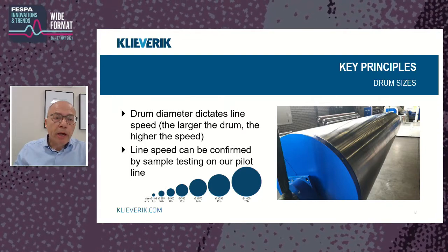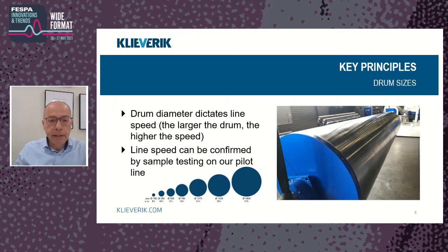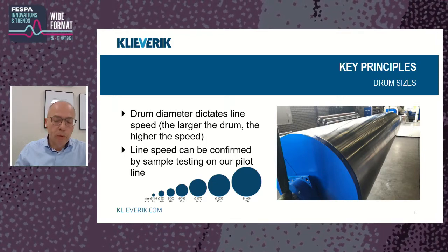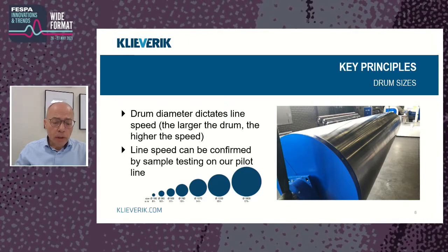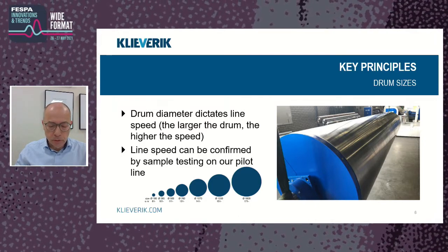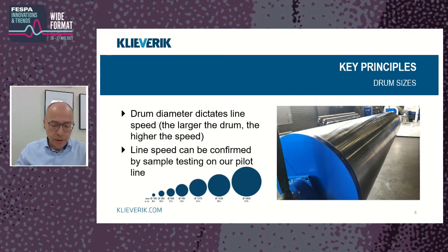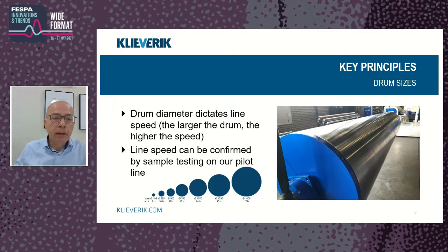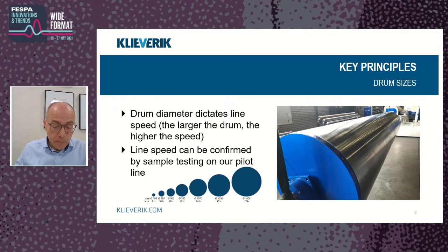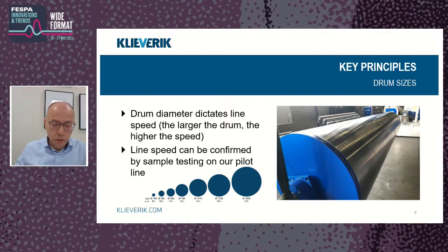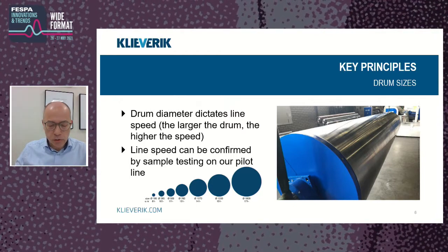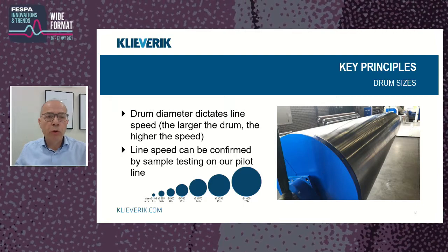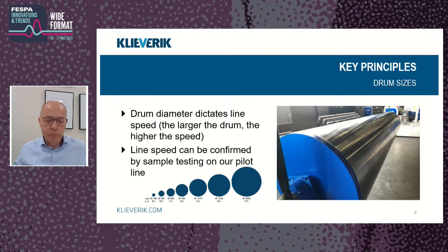We start with a small diameter, 200 millimeters, and that can go up well beyond 1 meter. Now the quality will be the same irrespective of the machine, and the diameter purely determines the output. They all work with thermal oil for its thermal stability, but against all rumors, no need to change the oil. It will last over the lifetime of the machine.